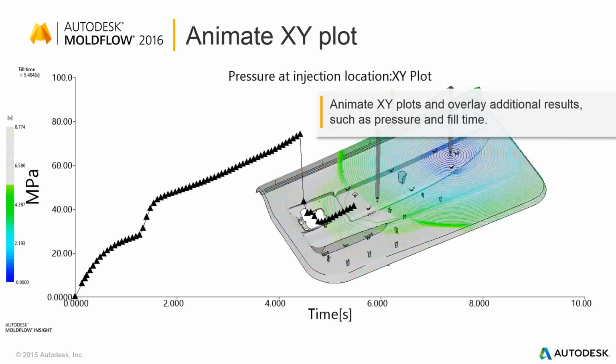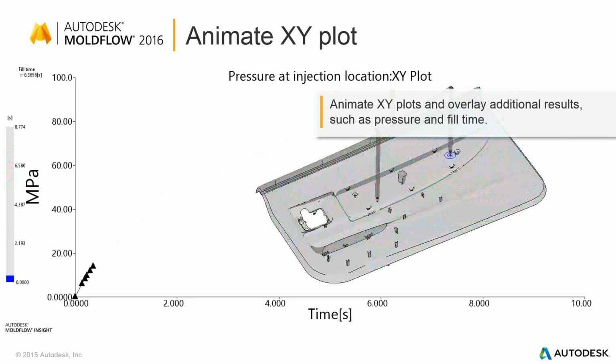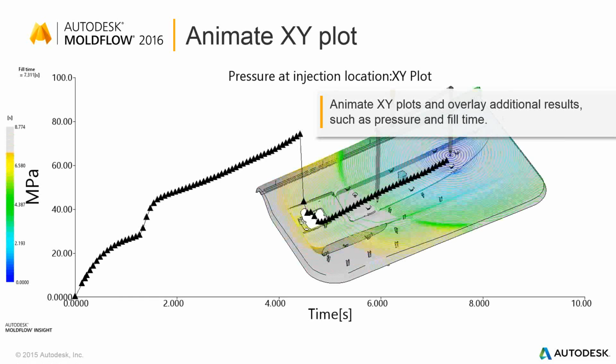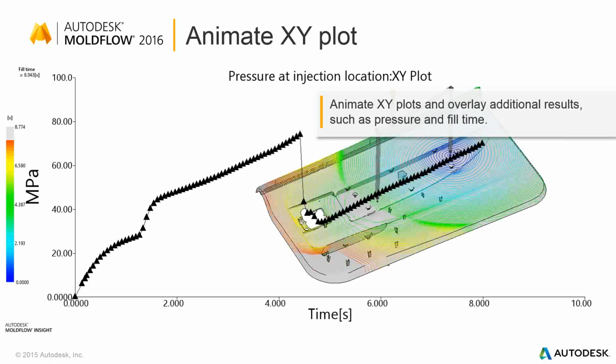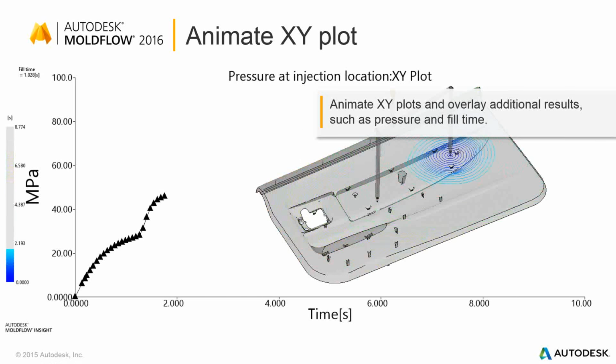So you're using the fill time plots to create an animation together with the XY plot. So it makes the understanding of the analysis a lot easier to see. Particularly for people that are not necessarily Moldflow experts, this is going to be significantly easier to understand what's going on.